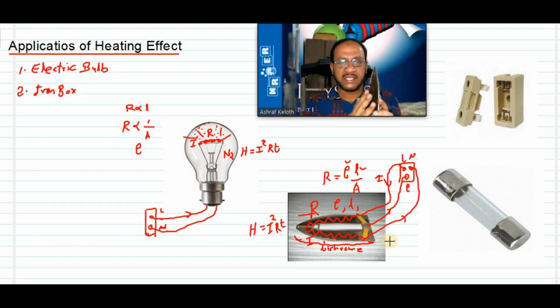So suppose you have some doubt, there is a chance for electricity on this surface. In such a situation, you don't touch like this. If you have a doubt that there can be electricity in that area, you touch from the back side only, like this. If you touch like this, your muscles will not contract this way. Muscles can contract only this way. So you may escape from severe electric shock. Got the point? These are all applications for your day-to-day life.